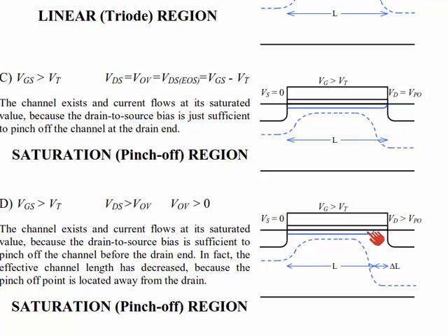And as you know, if we take a region of semiconductor and these two regions have comparable electron concentrations, but the case D channel extends a shorter distance than the case C channel, then we have a shorter channel in case D than in case C, and we have a lower resistance channel in case D than in case C. So we have, by this delta L difference in channel length, and delta L is typically a pretty small number, a small fraction of the total channel length for many high-quality transistors, typically less than 5% of the channel length, then we see less than a 5% increase in current from case C to case D.